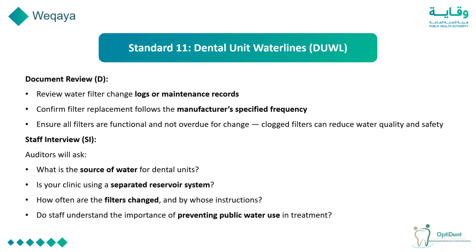So you have to differentiate, as I mentioned, independent water source, also named separate reservoir or independent reservoir, which is a bottle filled by distilled water, filled by the dental assistant, and it must be cleaned and disinfected with a special disinfectant once per week, while the municipal tank or container from 3 to 6 months.